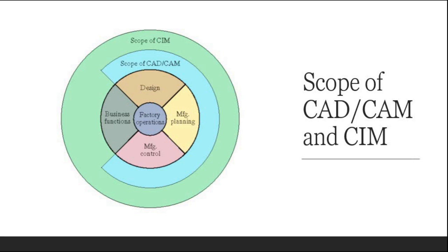Then the orders containing the specifications describing the product serve as the input to the product design department. The new products are then designed on a CAD system, and the components that comprise the product are designed, the bill of materials is compiled, and assembly drawings are prepared. Then the output of the design department serves as the input to manufacturing engineering, where process planning, tool design, and similar activities are accomplished to prepare for production. So many of these manufacturing engineering activities are supported by the CIM system.